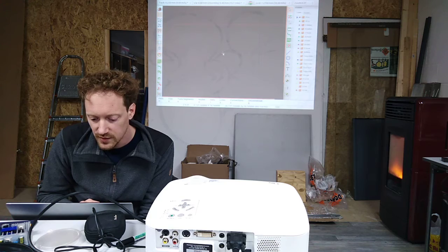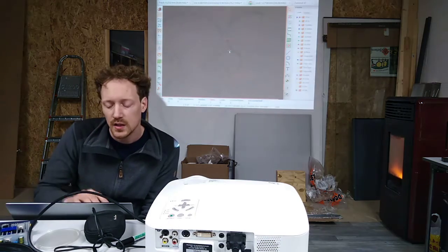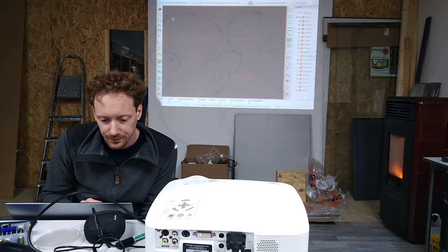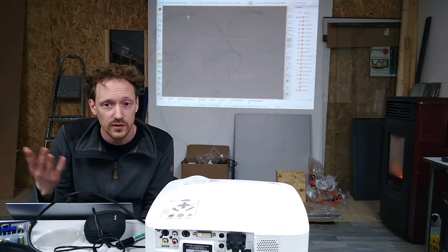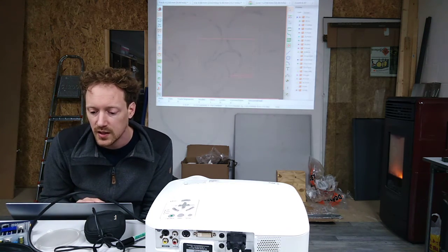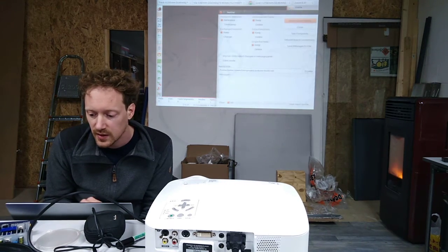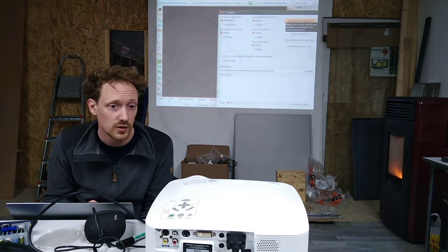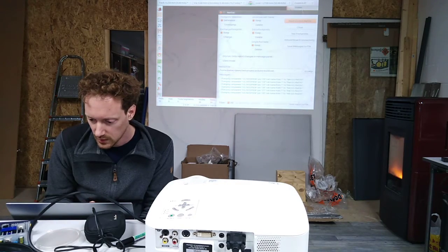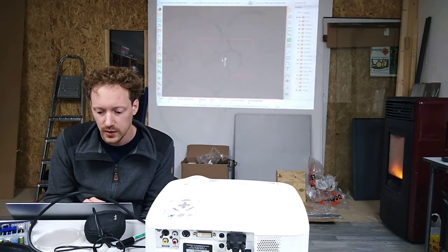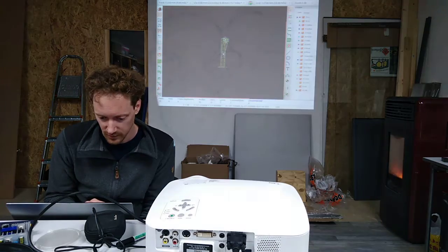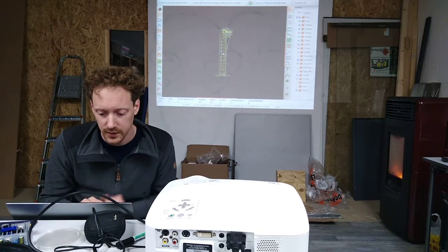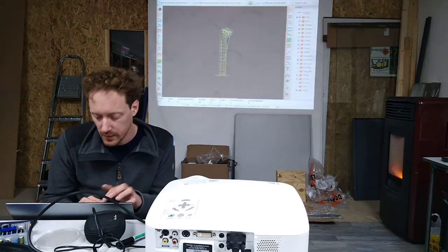Yes. So this shows the layout of our tool, and well, you can set the page settings depending on the size. So we might want to set it to 15 by 15, and now we can press here read netlist, and I'm going to just read the current one that we just created, and well, close it, and now we can see that we have all these components spread out over the board, and now we have to lay them out manually.